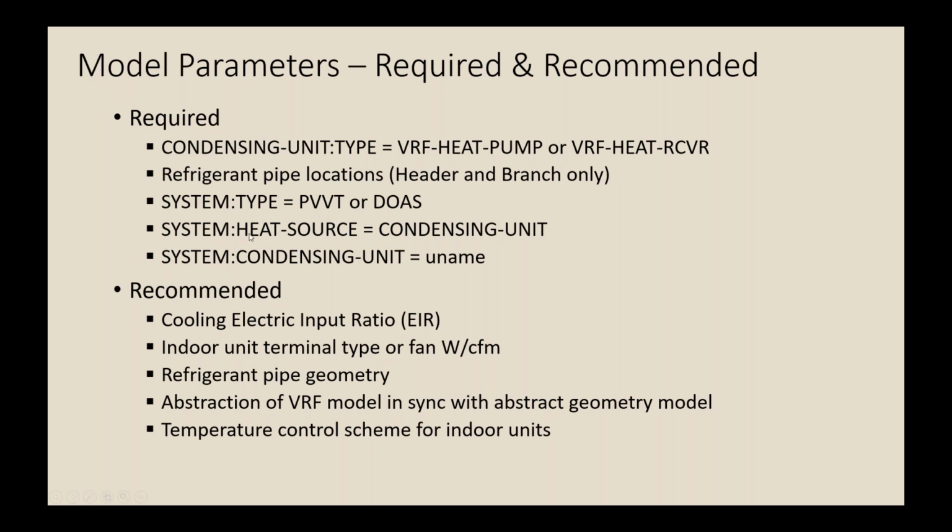And then, in order to set up a VRF in a specific system, you specify the heat source to be equal to condensing unit, and then the system condensing unit keyword is set to the username of the condensing unit that you want to assign to that system.